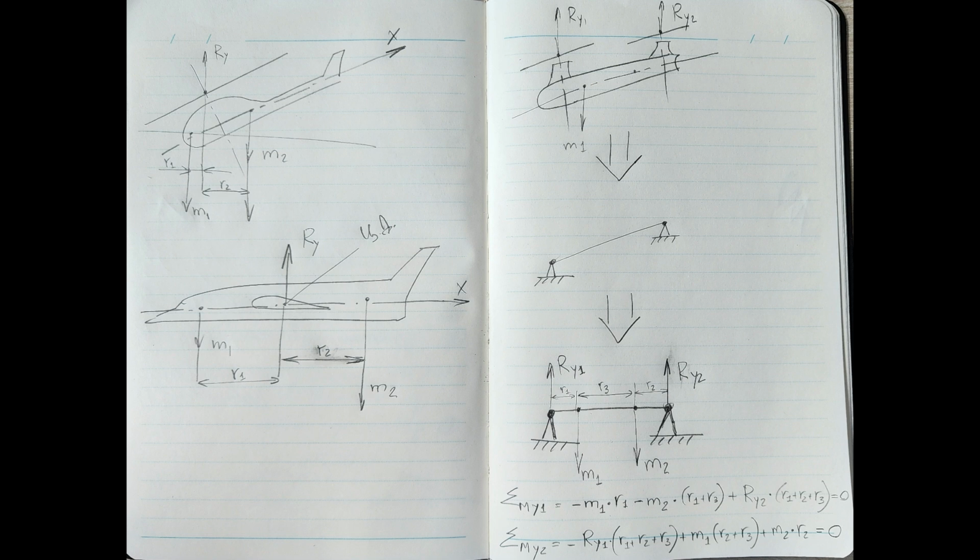In the case of an airplane or helicopter of the classical scheme, the alignment calculation is relatively simple and has the following order. For each component mass, a coordinate is determined in the general coordinate system of the aircraft. As a rule, all coordinates are negative, since the coordinate system is located at the extreme point of the nose cone.